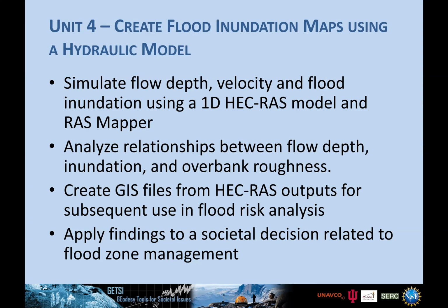And we tell them that what they have done for one cross section is sort of done for all the cross sections, and we go into some equations of HEC-RAS, and depending on how familiar you are with HEC-RAS, you can go deep into those equations. If not, you can just wave your hand and show them what is happening and how Manning's n is used.